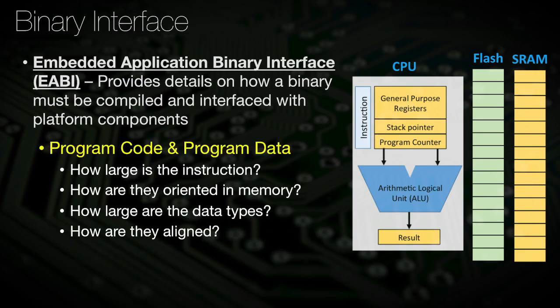There are specifications on how program code and data are physically sized and placed into memory. The C programming language does provide us with data types, but unfortunately these are not necessarily portable. Some data types have varying size, and a compiler may even implement these types as different sizes optimized for its architecture. The C standard types are actually not the standard way developers declare data, as they can be ambiguous. Even further, allocated information will be aligned within specific boundaries with memory.